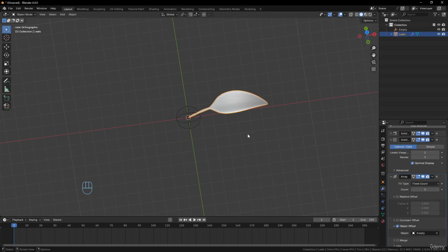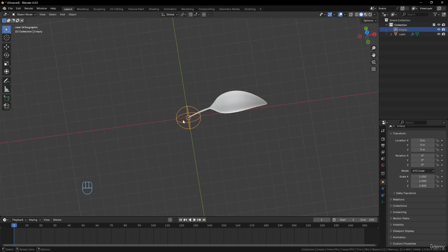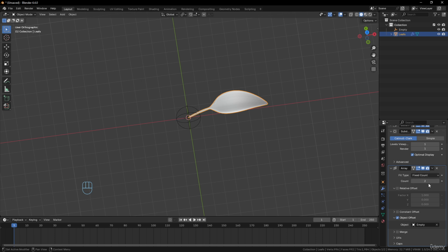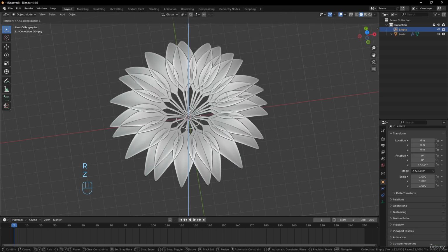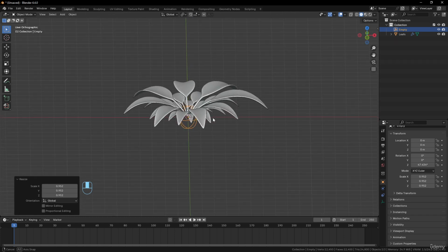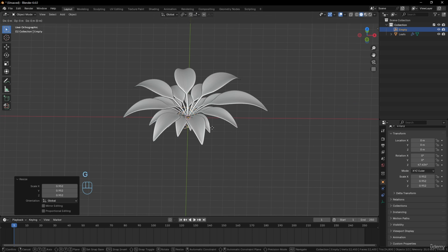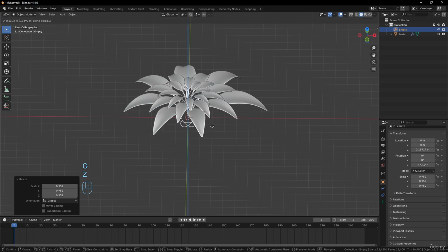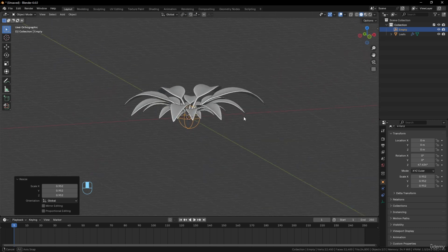For example, let's select this one, okay, and we will make this kind of rotation like this, put maybe 25 leaves like this, and we'll make a rotation with RZ like that, okay, and we will scale it down, okay. So this already looks almost like a plant, really easy, okay. Just put it up a little and you will have this kind of nice shape that looks already natural, okay.